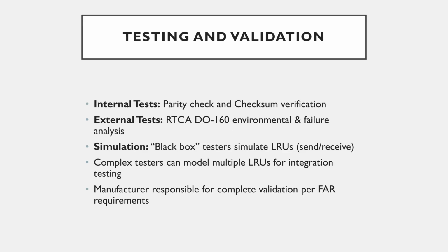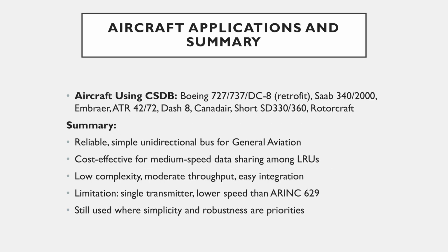Testing includes internal checks like parity and checksum validation, and external checks defined in DO-160 environmental standards. Black box simulators emulate LRUs to verify timing, message formats, and error handling. Full compliance must be demonstrated during system certification.